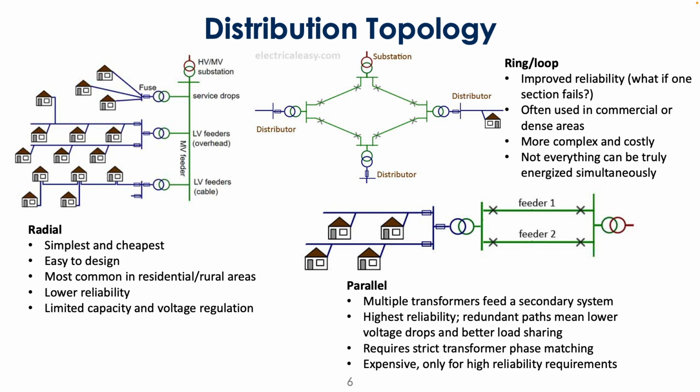And so you can imagine the electricity going through that feeder is essentially propagating with a particular frequency in sync with the rest of the electricity grid. And you cannot actually have multiple lines that would be operating even at the same frequency but out of sync. That physically would not work. You would end up, depending on where you are in the system, blowing lots of things, damaging equipment.